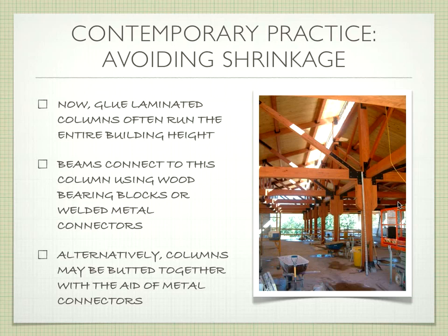If it's plywood or a slightly different way of building up that floor, it's not in the same fire rating category. As soon as you mix in some other method, you lose the fire rating. So in this instance, all it is is heavy timber, and there are some disadvantages to that. We'll talk about it in a second. There are no wall cavities. This decking or planking is actually going to be thicker, at least 2 by, sometimes 3 inches. Not nominal 3 inches, but a full 3 inches.